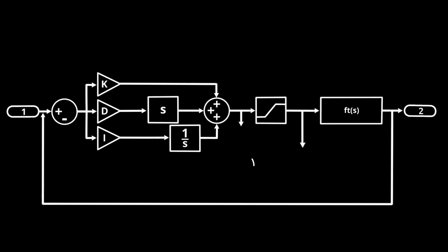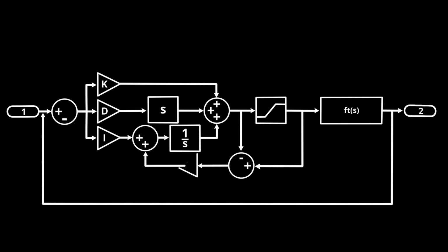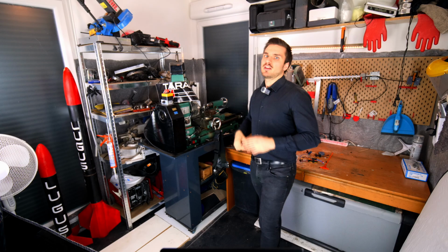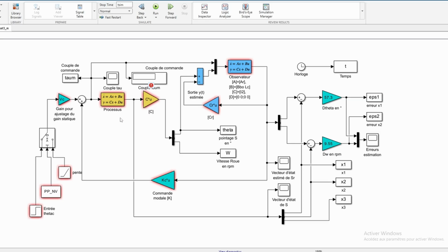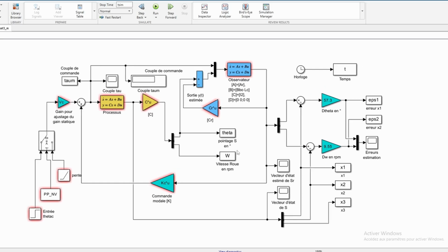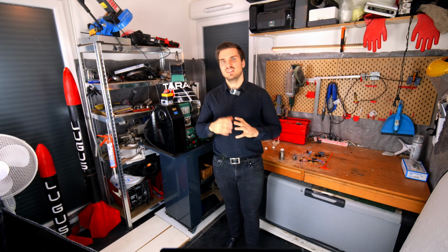And that's what the anti-wind-up does. We use the back calculation method, where basically we calculate the value of the error, which is overestimated, and subtract it from the error sum of the integral, with a small gain named k wind-up. To determine this gain, the best way is to add it into our Simulink, add some saturation, and try several values in multiple simulations. Except that this is true once again for a continuous PID, but we are not continuous.